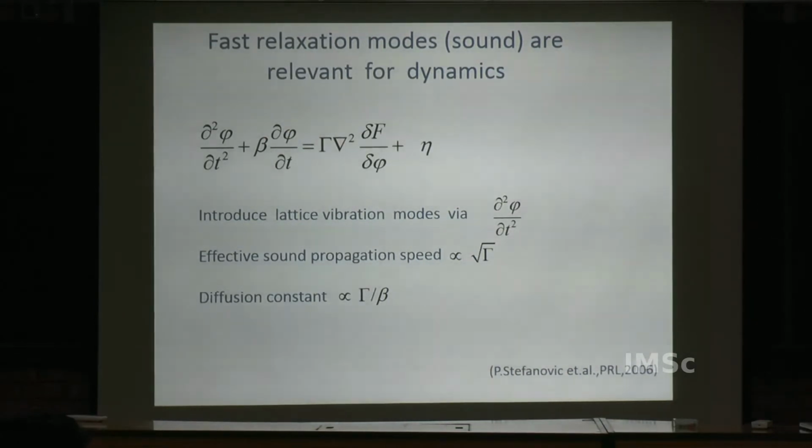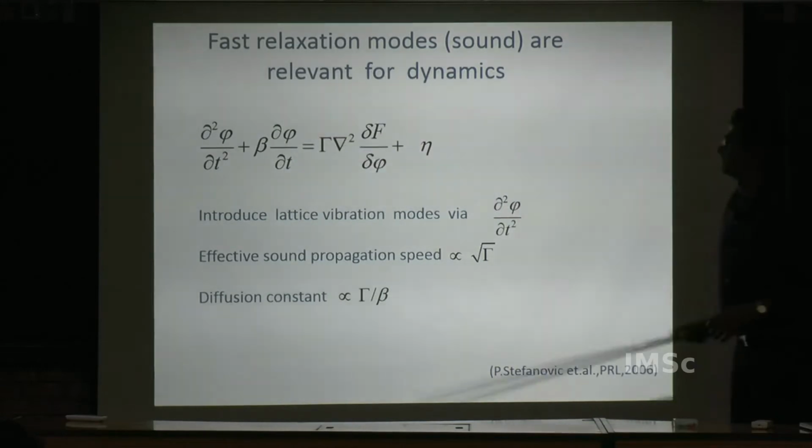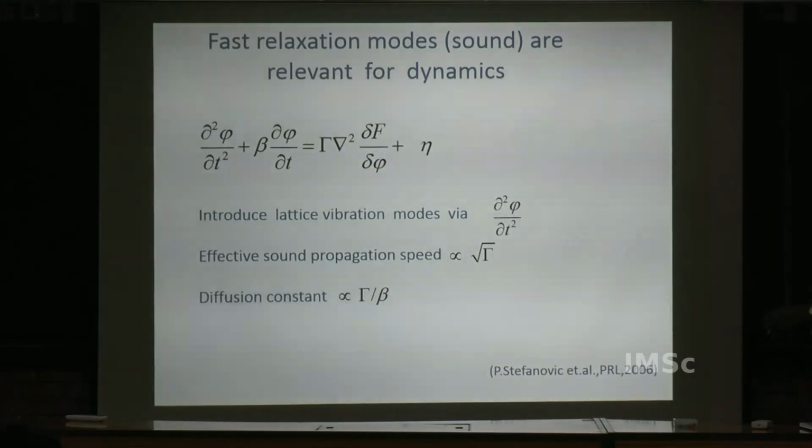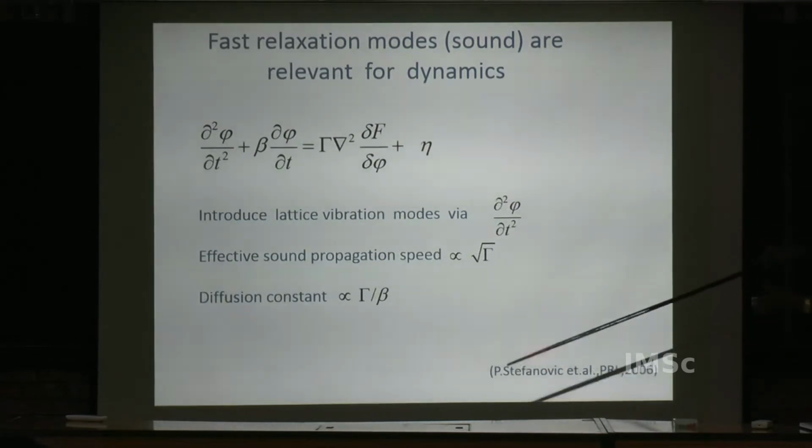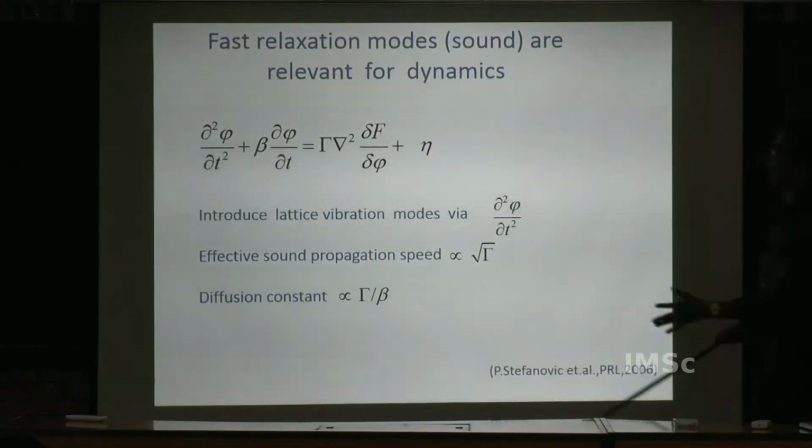Now in normal hydrodynamics of liquids, let's say very simple fluids, there is a momentum conservation equation, which is Navier-Stokes, and there is a continuity equation, and there is also an energy equation. If you combine all this, you will get a second order equation in density, and it will show that there are damped sound modes as well as diffusive modes. So here also one is bringing in that feature by introducing this term in a somewhat ad hoc way.